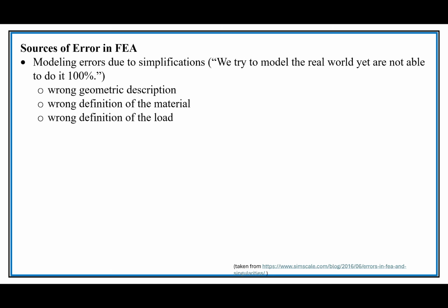The load, if you're looking at reality, you have to make some type of assumption about what the forces and torques and external loads are going to be on a thing. It is not always clear what the case should be. You might have to run a number of cases and simplifying assumptions to be able to get a definition of the load. Boundary conditions, similar.